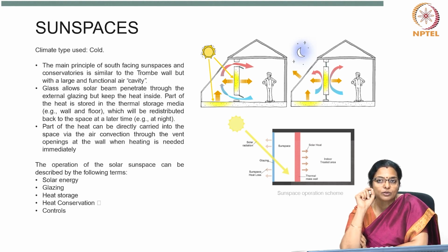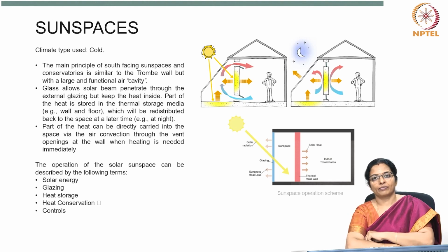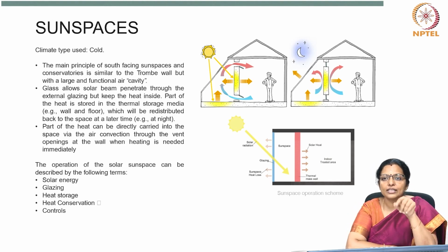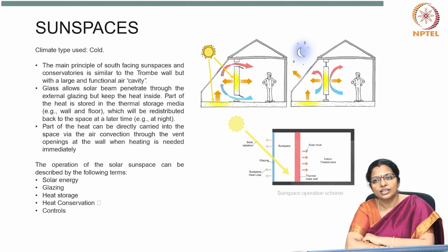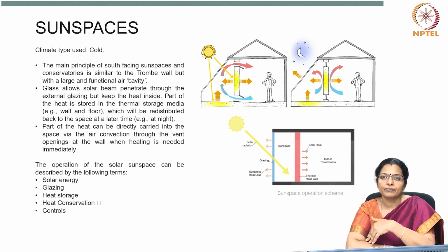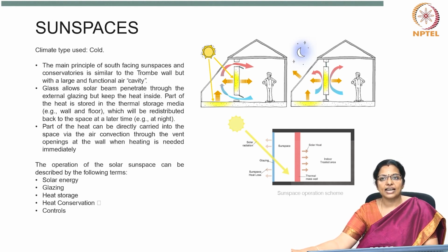Orientation must be proper. So, in order to achieve optimization in design, the glazing has to be perpendicular to the radiation received at any time. Heat storage: the first phase of the heat storage procedure is the solar radiation absorption. The surface color and texture are the two main parameters that affect the absorptance. Dark colored surfaces are generally higher in absorption than light colored. The heat storage medium should be very effective, and this is higher when the direct radiation strikes the surface.